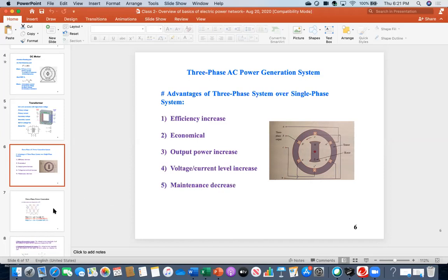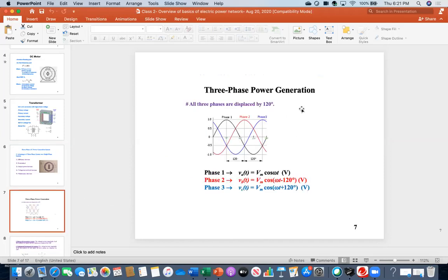Okay, so now moving forward. Now you know that three-phase power means AC power with sinusoidal voltage. So how does the voltage look? Although I have given the names phase 1, phase 2, phase 3, these are basically phase A, phase B, phase C, according to the three-phase system. Everybody see, for example, this is the 0 point, look at phase 1. It starts, goes up, comes down, and then back. This is called one full cycle, 360 degrees.